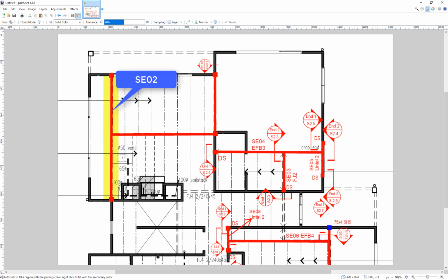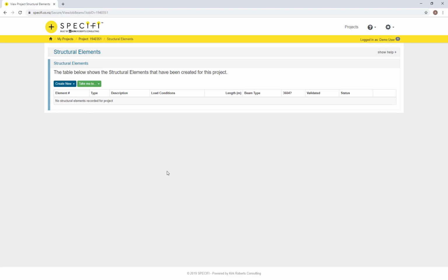This second beam is 5.2 meters long and is supporting two roofs, an upstairs wall, and a portion of a floor that is parallel to the beam. The point load is located in the middle of the beam at 2.6 meters. End 1 and 2 are both supported on posts, which land on the external two-story foundation of the house. Let's start by designing beam 1, the beam over the lounge.